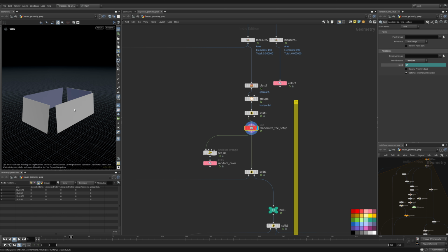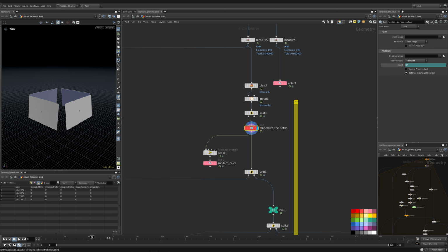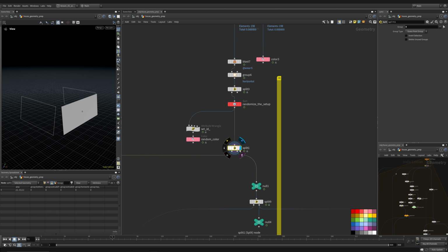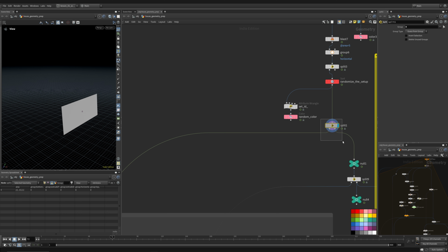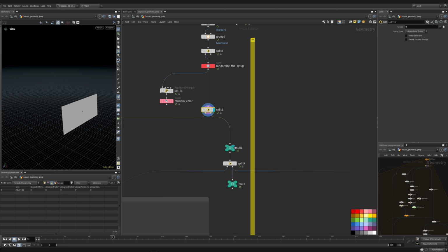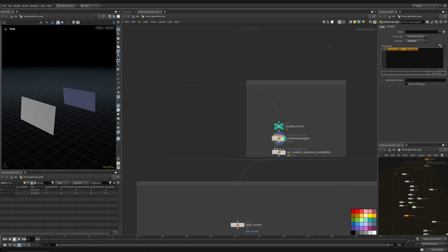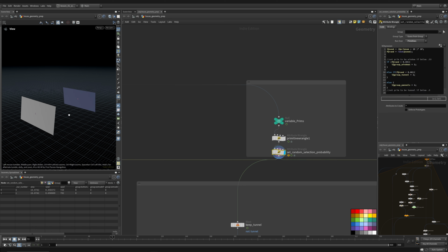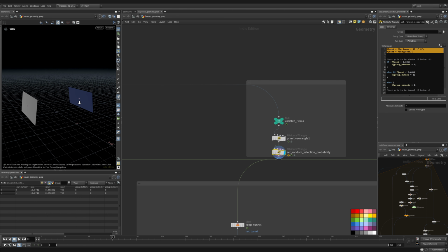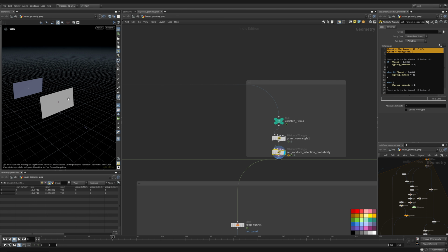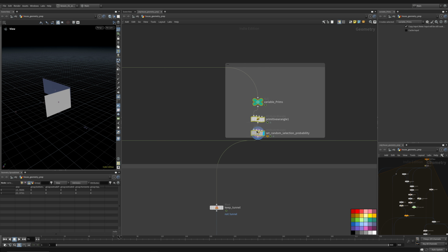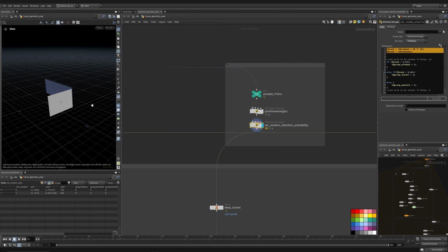Again, we sort our primitives randomly, and we sort them randomly so we get a random seed for each frame. And then we're splitting at 1, which when we select a split node, the left input is what is previewed. You see the right, split it again, the right. Now we get 2 primitives, and then we're assigning our random number. And this, remember, we showcased because we had that little issue last time we actually fixed, where we were multiplying our primnum by the frame number, which gave a constant seed for primitive 0 on every frame. So we actually debugged this together, and I showed you why we needed to fix this to actually get the result we were expecting.